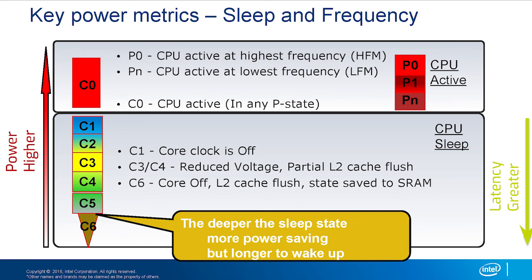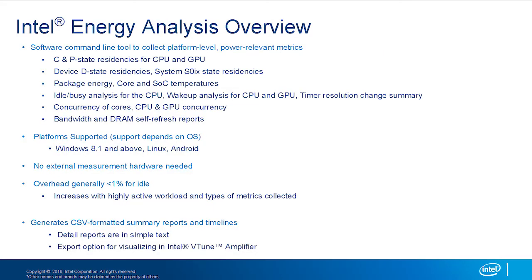state to go into. So as mentioned, the SoCWatch data collector can capture all of the C and P states for both the CPU and GPU and different device states and packaging temperatures. There's no external hardware necessary for this data collection, and it's very low overhead. And it outputs detailed reports in text CSV format, and it's capable of reformatting the output so it can be imported into the VTune Amplifier for visual representation.